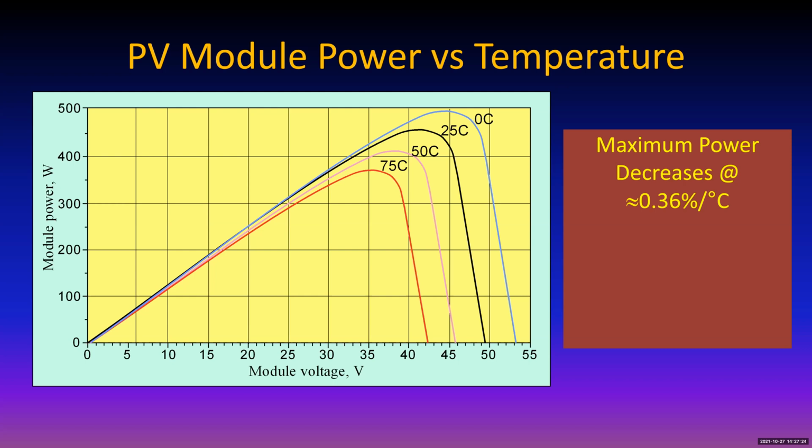So you can design your equipment with that knowledge: your inverter does not have to be as big as the power output of the modules, because they never get there. Even if they do, the inverter simply says, you're trying to give me 10 more watts than I want to process, so I'm just going to reject those 10 watts by bumping you away from your maximum power point.